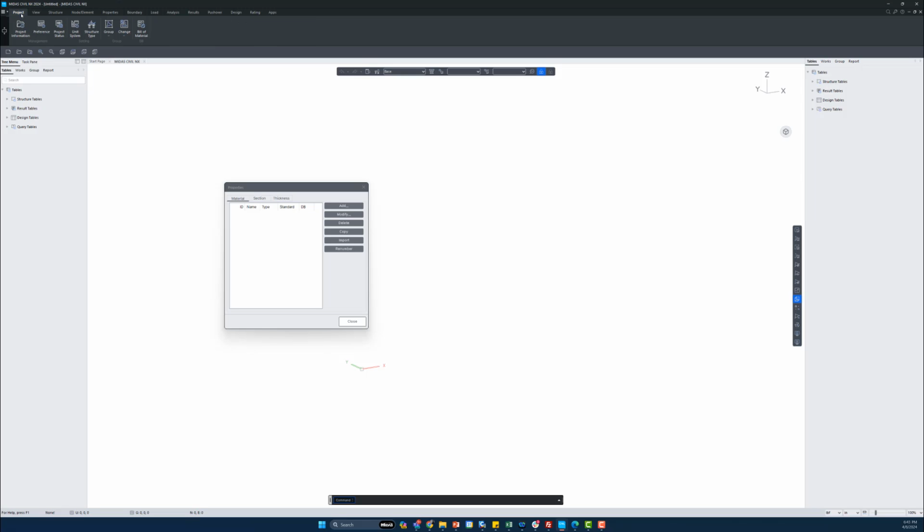You can also do that under Project, in the Unit System. If you click that, you can change the force and length unit systems there. But if you want to do it a bit faster, you can use the right hand end corner. Once I define the unit system, I can go back to defining my material properties.